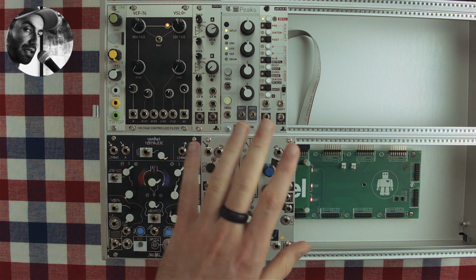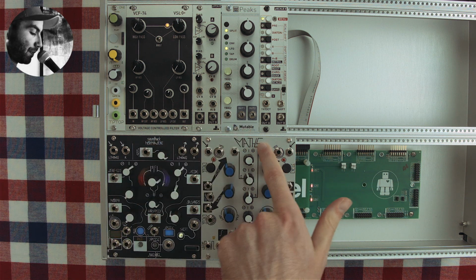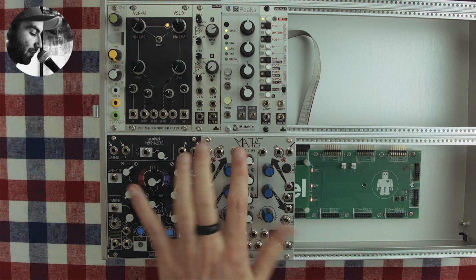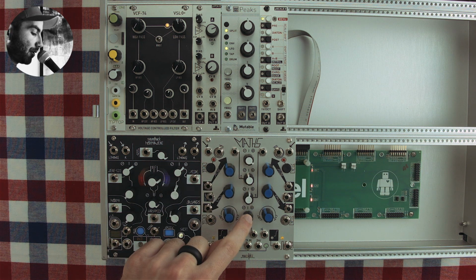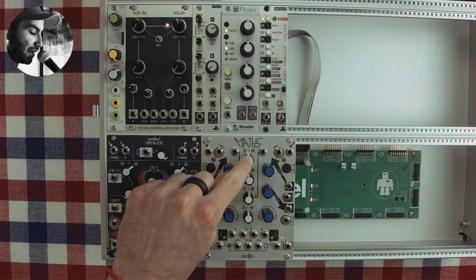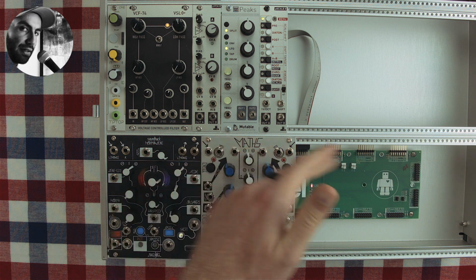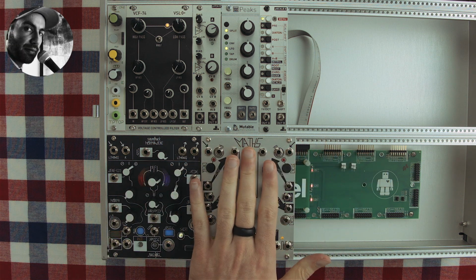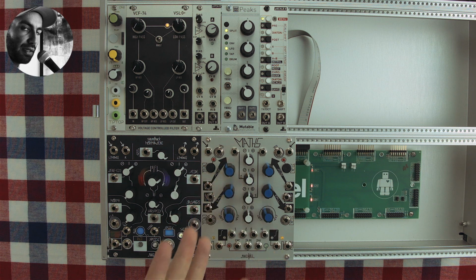Channel 2 and 3 are much simpler. So you have the channel 2 input here, channel 3 input here. And in the middle here, you have these 4 attenuverters which map to the 4 channels. So you have 1, 2, 3, and 4. And if you remember the equation I mentioned at the beginning, so the AX1, BX2, CX3, and DX4. The A, B, C, and D are basically these 4 attenuverters, and X1, X2, X3, X4 are the 4 channels respectively. So I like to think of the maths as basically just constructing the parameters that feed into these various